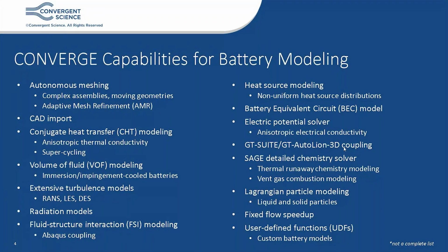If you're looking at steady-state temperature solutions for battery systems, we make use of the supercycling approach that accelerates these steady-state solutions for solids. Innovative cooling designs like air-cooled and liquid-cooled batteries can be investigated using the 3D CHT modeling capabilities, and new cooling designs like immersion or impingement cooling can also be investigated using Converge.